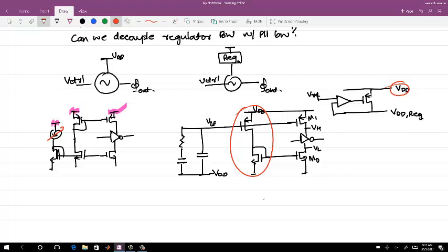Inverter not being equidistant is not a problem. Effectively here the inverter is equidistant from the regulated VDD with respect to ground, right? So that's not the problem. Earlier you were having only one current source with respect to the given VDD supply and the ground and the inverter high voltage. Whether you are regulating current or regulating voltage, in the end, effectively it is doing the same thing.